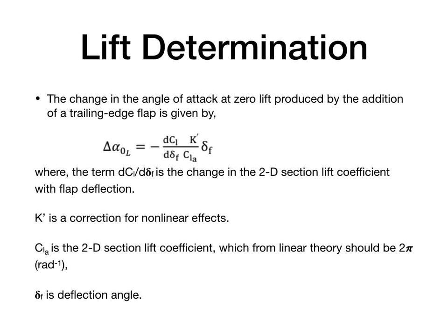The effectiveness of any of these passive and active devices depends on their deflection angle delta f, the wing thickness to chord ratio t/c, the ratio of flap chord to wing chord cf/c, and the wing sweep angle and aspect ratio. In most cases, the ratio of flap chord to wing chord is approximately 0.3 and the maximum lift occurs at a deflection angle of 40 degrees.